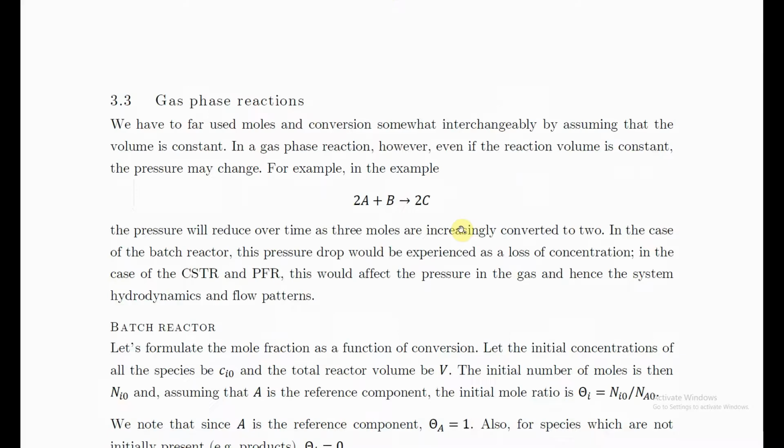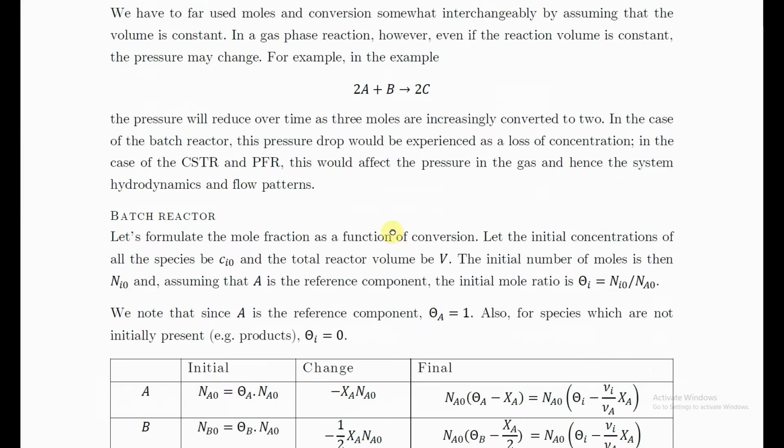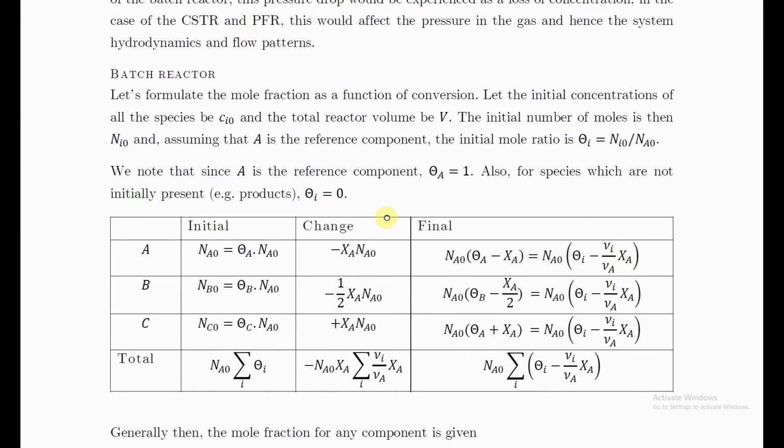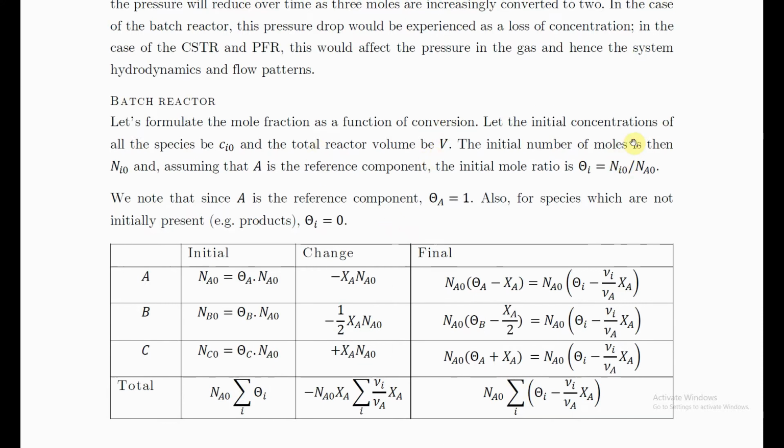So coming back to what we're looking at here, let's start with the batch case. And let's think about, first off, we spoke quite abstractly when we were defining our reference flow ratio. So in the batch case, we are not talking about flow, right? By definition, there's no flow through a batch reactor, so we just talk in terms of number of moles. And in this case also, because there's no flow, we are not talking about inlet. We are talking about the initial amount with respect to the basis component.